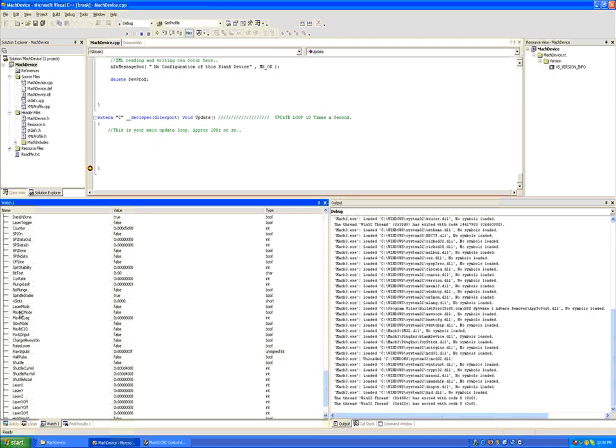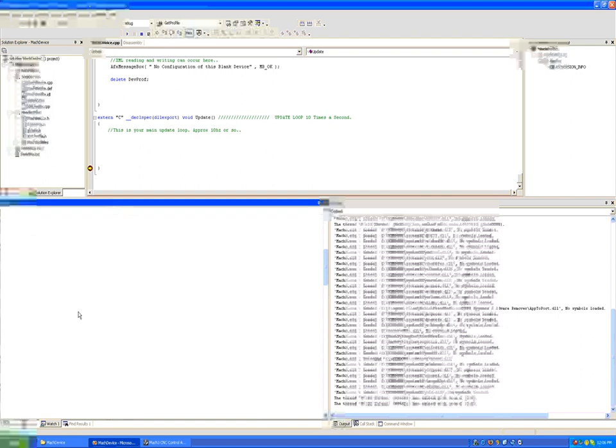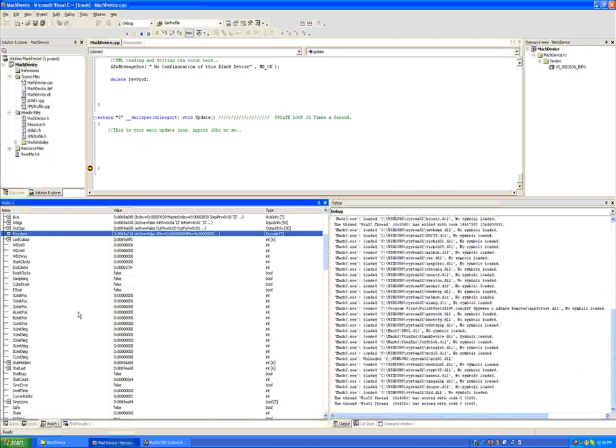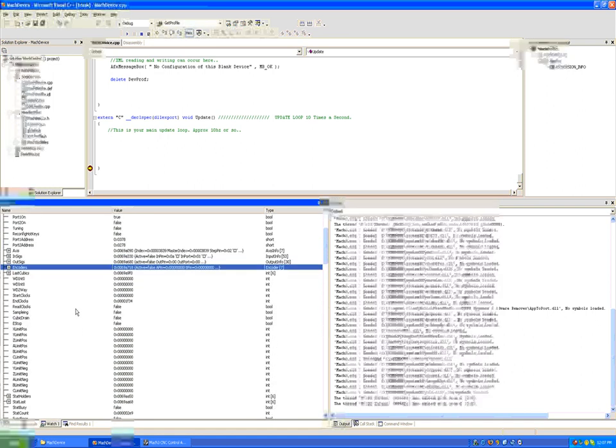You can see, for example, a variable max NC mode set to false. If we were in max NC mode, that would be set to true. These variables are read by the kernel's ring 0 25,000 times a second in 25K mode. So changing one of these variables can make an instantaneous change in movement to the system.